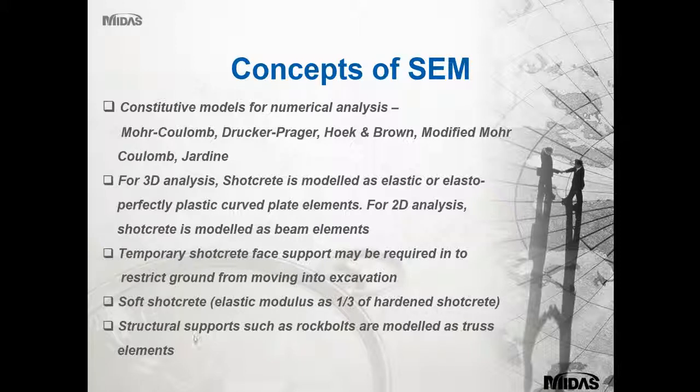Rock bolts are modelled as truss elements. If there are steel lattice girders in place inside the shotcrete, then the combined stiffness of steel reinforcement and shotcrete is used as equivalent shotcrete stiffness.